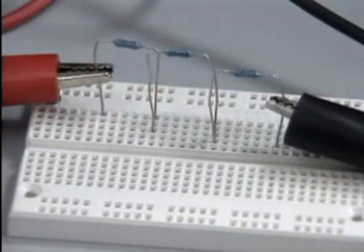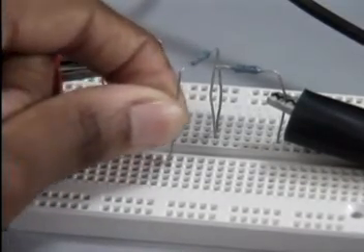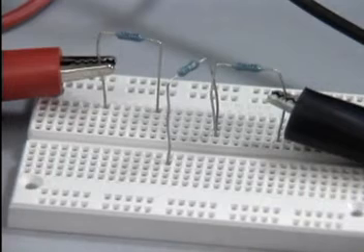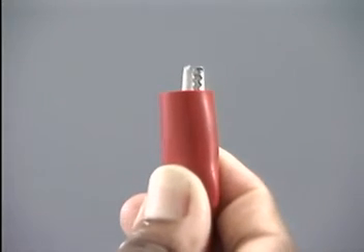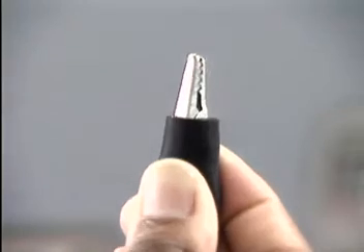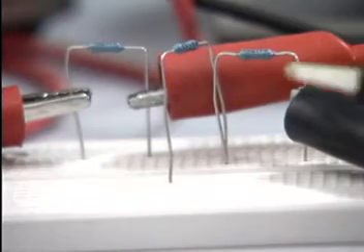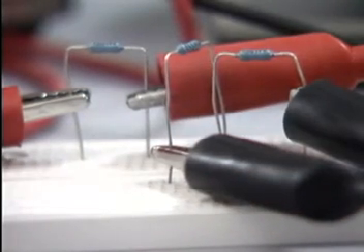Now, open up the circuit between the 1,000 ohm and the 1,500 ohm resistors. To do this, lift the left side of the 1,500 ohm resistor out of the common group of 5 and reinsert the axial lead into a group of 5 below the center canal in the breadboard. This will ensure the proper separation of these 2 resistors. Now, take the red positive lead of the ammeter and connect it to the right lead of the 1,000 ohm resistor, and take the negative black lead from the ammeter and attach it to the left axial lead of the 1,500 ohm resistor. This will complete the circuit once again.